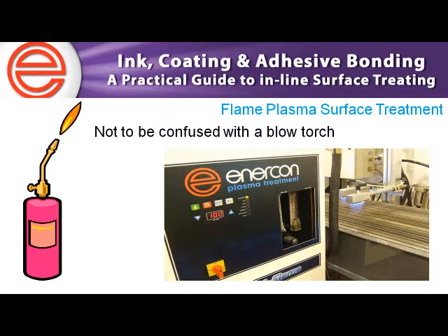There's really three pieces I'd like to point out, and I'll dive into the details of the flame plasma system. By going to a flame plasma system, it is of course safer for both you and your employees. It is consistent, so it's not subject to human error, and it's a very controllable gas mixture that's coming out of the head.